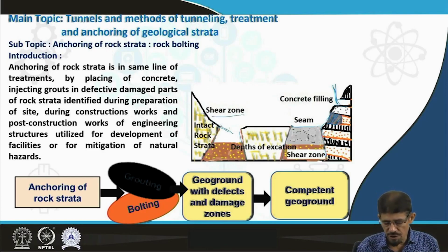In case of shear zone and fault, we are going to first excavate the damage zone or shear zone, which is a weak zone due to presence of deformed and fragile rock materials. Similarly, fault zone also has fragile fault gouge material, deformed and damaged.